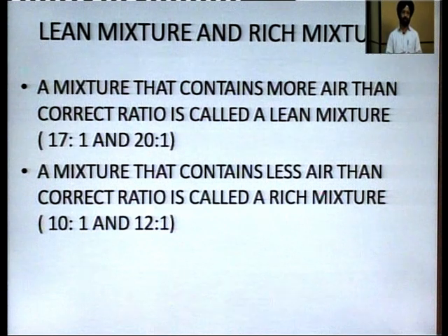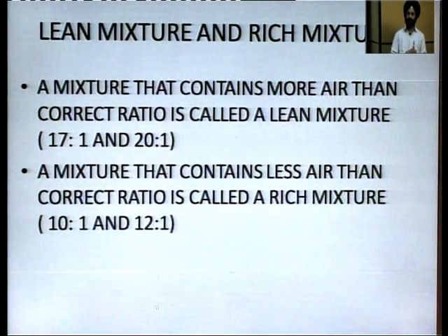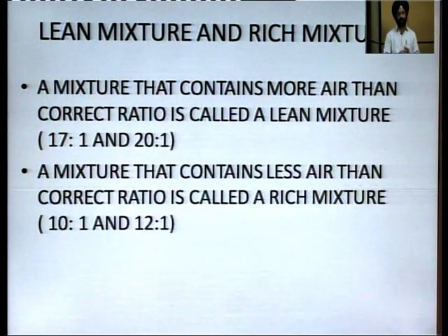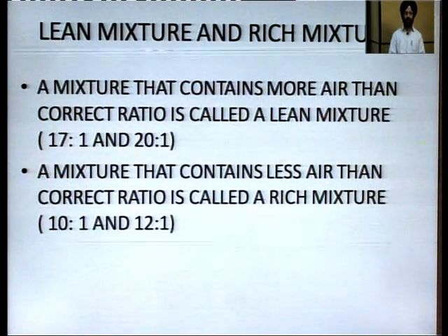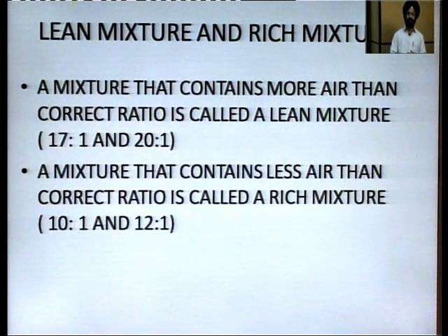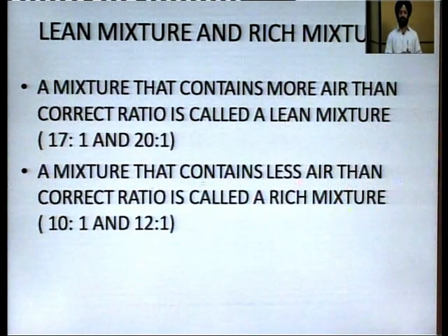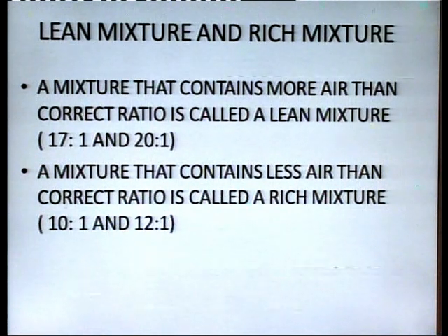So the question is, which type of mixture would we like to supply our engine most of the time? What do you think? The answer is lean mixture. Naturally, a lesser amount of fuel gives us good energy and good fuel economy, so we save on fuel costs. Our tendency will be to run the engine with the lean mixture, or at the most a chemically correct mixture, and not with the rich mixture, because the fuel will not burn completely when it is rich, as oxygen is not available. So fuel will go waste.